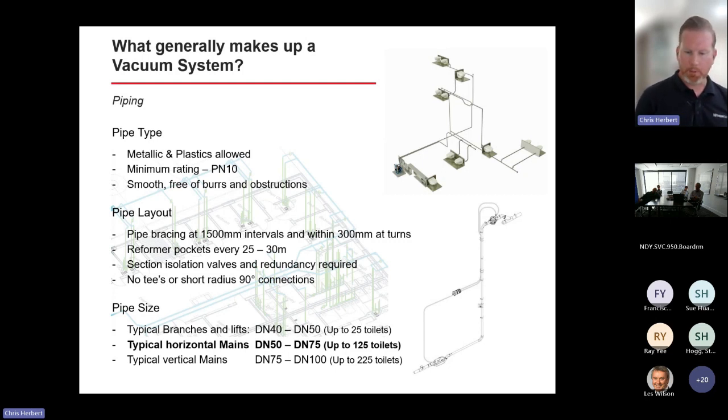And that's not about a burst, that's about collapse. Now, globally using PN10, we've never had an issue with collapsing pipes. And we've put that in the standard. What can happen is, because that pipe network is constantly in that subatmospheric condition, there's actually external pressure on the pipe rather than internal pressure pushing out. There's an external pressure pushing in.